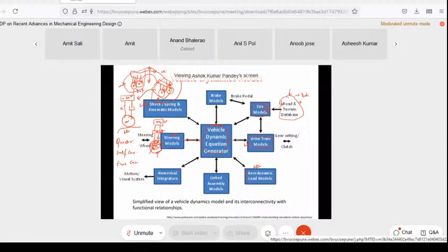And why is it essential? It is essential because you really need to find out that there will be some modes of the tire which will generate noise, right? It will generate some kind of vibration, and that will get transferred to your upper structure, and cause disturbances either in terms of vibration or in terms of noise. You have to go to that level of degrees of freedom, right? And then consequently you can just get the same modeling for all the four wheels and then do the analysis. So this is where one has to be clear what is the frequency range we are looking for to analyze our vehicle.